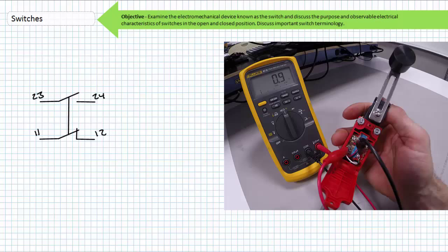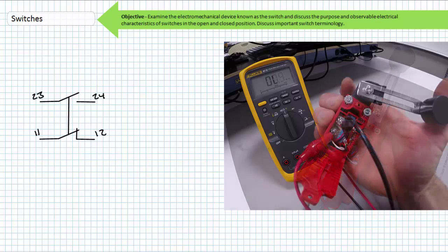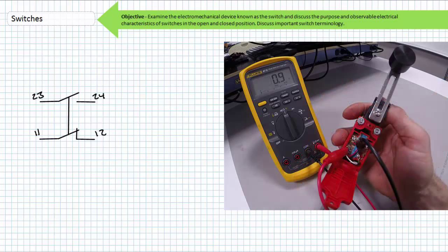What is interesting to note about this particular limit switch is that it can also be actuated from the other side. When I torque the arm in the other direction, the ohm meter indicates an open from 1-1 to 1-2, meaning the normally closed switch has been actuated into its active state of open. Again, when the arm is returned to the center, the ohm meter indicates the switch is returned to its deactivated closed state, supporting our earlier observation of this being a momentary switch.